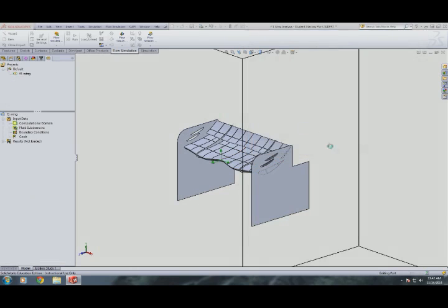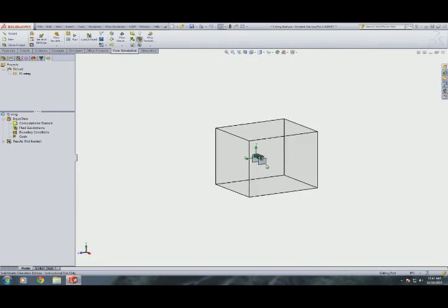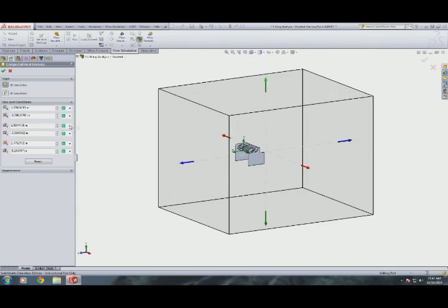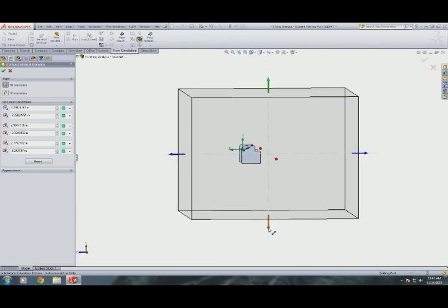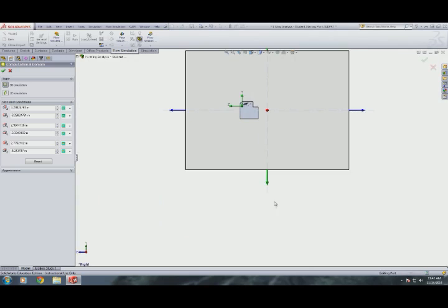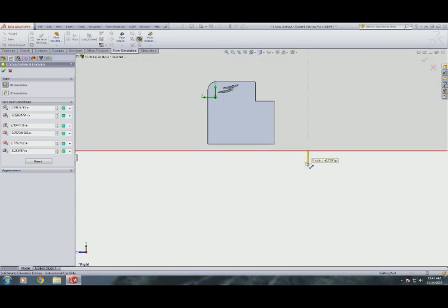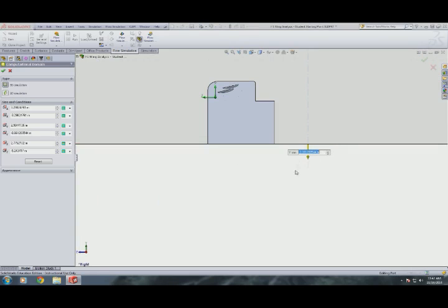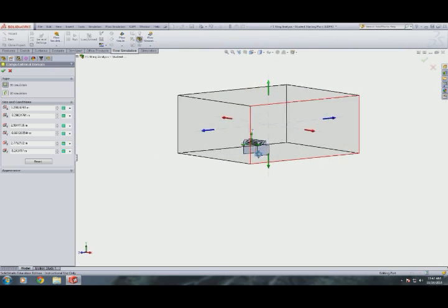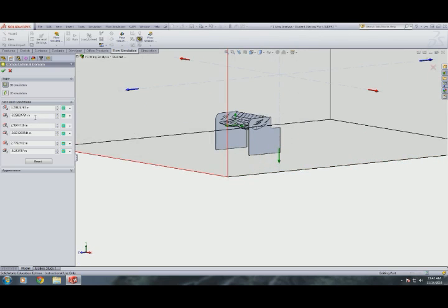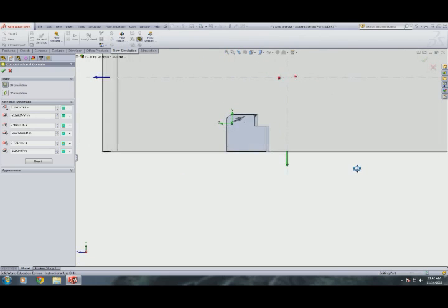And we get the wall around it. So to emulate the ground surrounding this thing, we need to edit the computational domain, and I'll just drag this arrow up a little bit. Mistakes have been made. And again, I'm going kind of fast because this is a video. You can pause it, you can rewind it. I don't want to waste anybody's time. I want to make this as concise and as efficient as possible, which is why I'm blabbering right now. Okay, so that snapped to the bottom of the wing. Actually, I think I gave it a specific distance, didn't I? Yeah, 0.8. So y minus 0.8 elevates the wing above the ground a little bit.